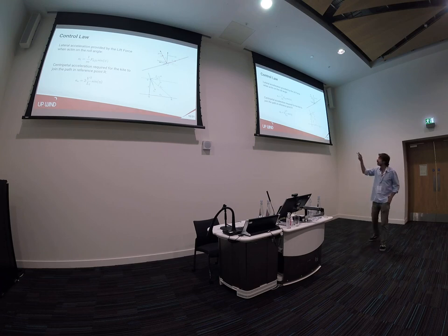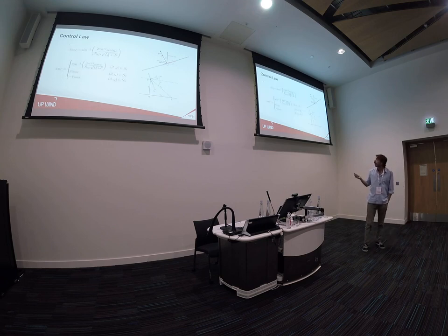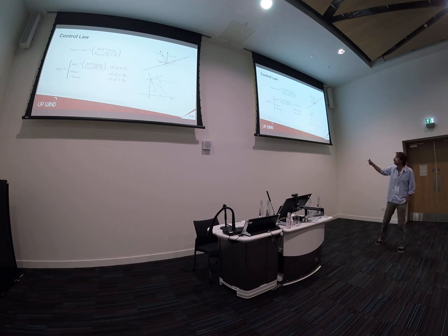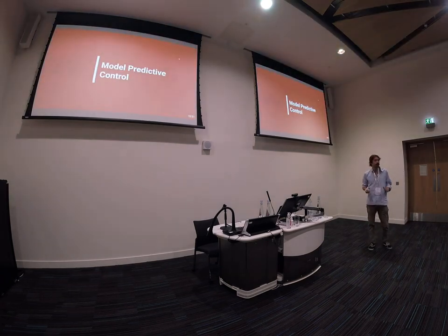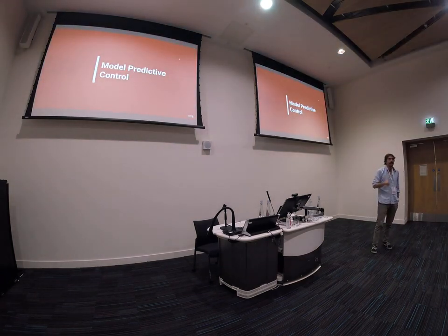And if we set that acceleration equal to the acceleration of the guidance logic, basically the centripetal acceleration to join the path, and solve for our roll angle, our control input, we can find a reference roll angle, and then we can define a control law, which is here with saturation. Okay. So basically, this is our basis controller.